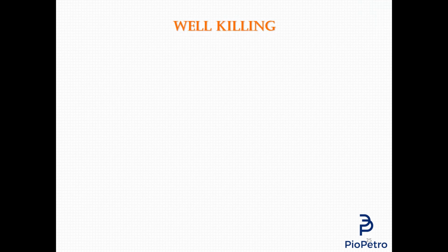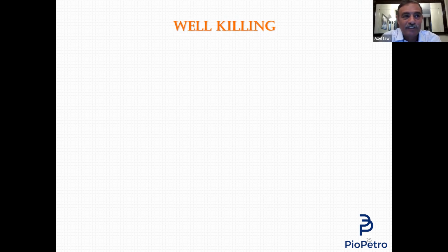Someone asking about the DHSV, also used during drilling besides production? The safety valve, downhole safety valve? A downhole safety valve does not exist in drilling. It does exist only on production wells, where we have an extra safety device that we put below the surface to protect us from ourselves. And we can open and close it using a control device, a control panel. This device, we use it in production wells only.